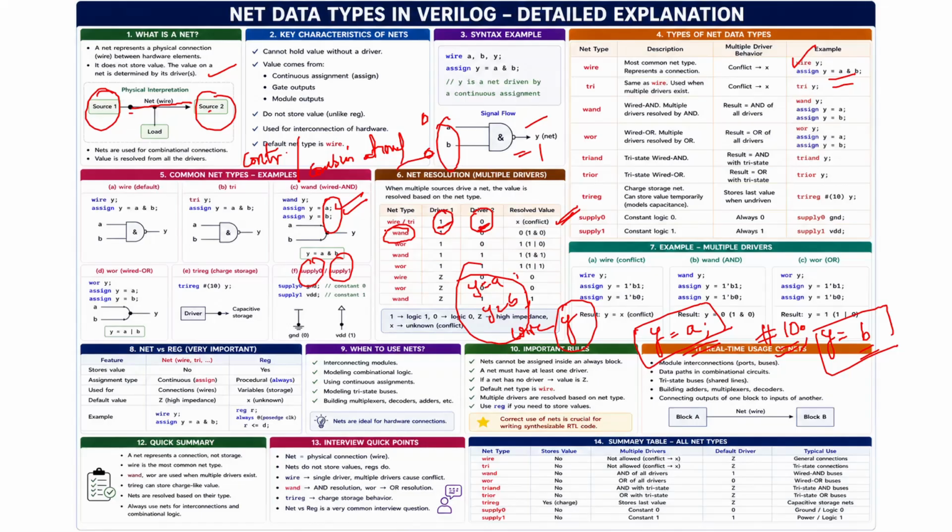In I2C, I told you, we are using a wired AND gate. In this wired AND gate, whichever one is taking low will be the active mode, because 0 and 1 means wired AND. It is an AND gate. Sometimes you are driving 1 and sometimes you are driving 0. Then there is no conflict here, right? So we will get the output either 0 or 1, because you are driving y equal to 1 and then y equal to 0. So this is wired AND that I am taking. So wand.